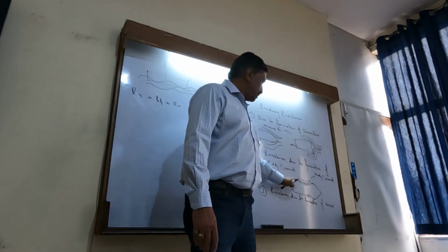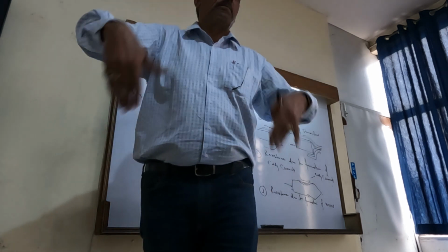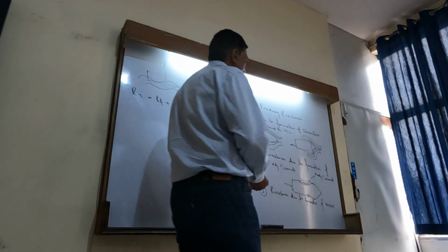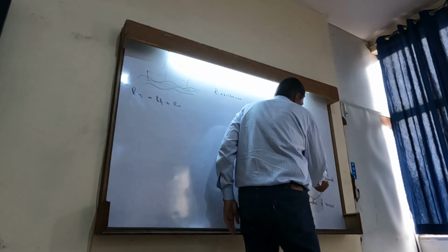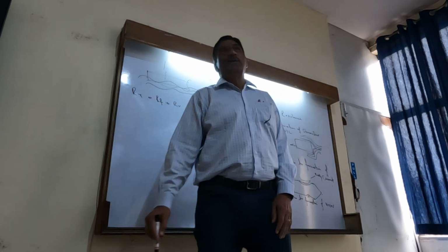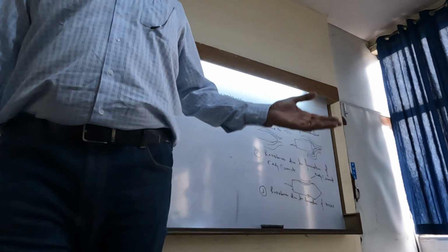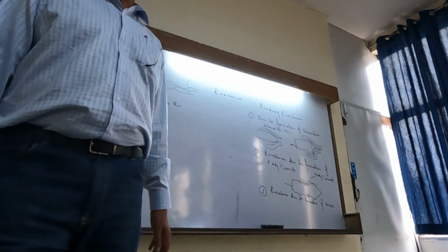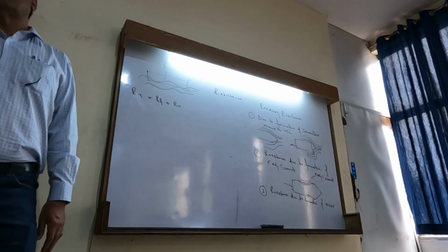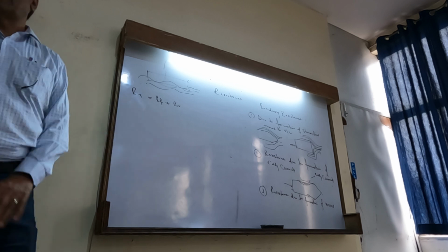This is just to illustrate change of cross section. Even if it need not be abrupt, as long as there is a change of cross section, the waves cannot move smoothly, which they would if the whole thing is streamlined. Same thing is true for aircraft also. That is why we say aerofoil structure and all. This is only streamlining because there the air is moving, here the water waves are. So this is the total resistance of the vessel.